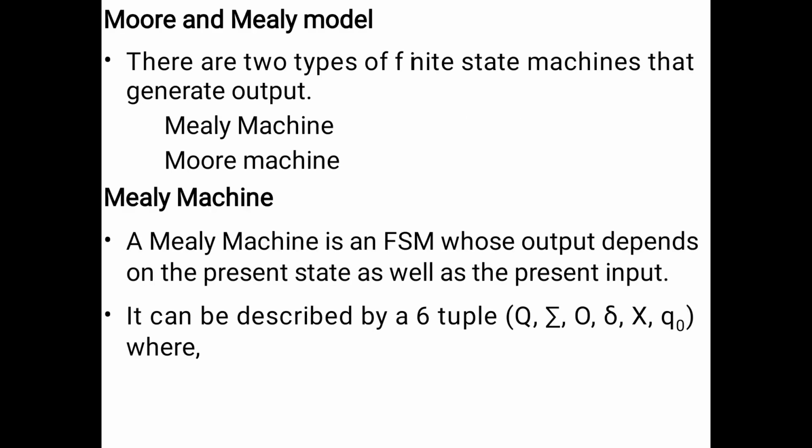There are two types of finite state machines that generate output. They are Mealy machine and Moore machine. A Mealy machine is a finite state machine whose output depends on the present state as well as the present input.